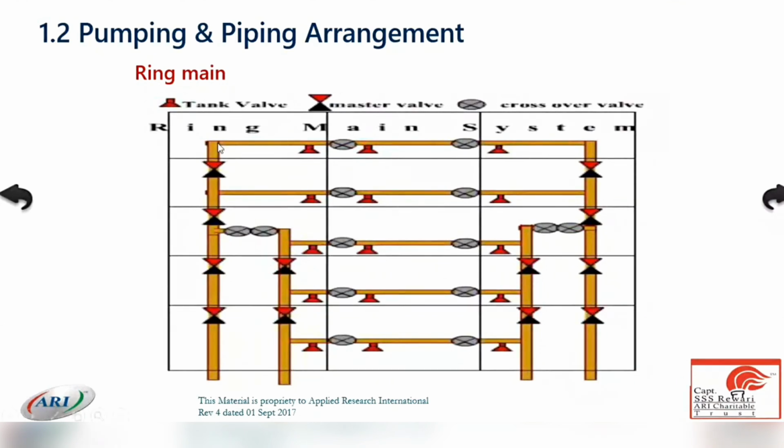Various crossovers, there are too many valves you can see in the line. So many pipelines are used. There are a lot of ways of discharging one tank. You can use the port side line, you can use the starboard side line, you can use the middle also if you connect it. You can connect it from here also. Each tank has various ways of discharging so as to maintain proper segregation.